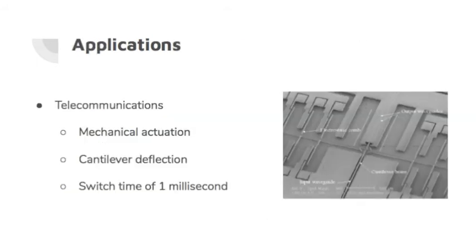In telecommunications, one application is mechanical actuation. Here, the input channel guide is fabricated on a cantilever suspended over an edge cavity. Surface electrodes deflect the cantilever from side to side electrostatically to allow connection to one of the two output waveguides. Switching times are of the order of milliseconds.